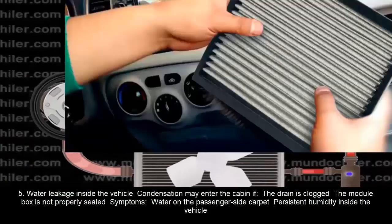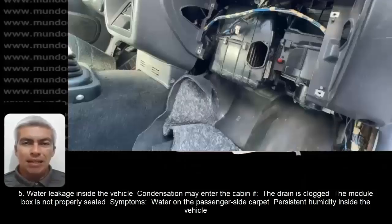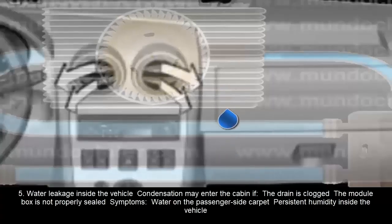5. Water leakage inside the vehicle. Condensation may enter the cabin if the drain is clogged or the module box is not properly sealed. Symptoms: water on the passenger side carpet, persistent humidity inside the vehicle.